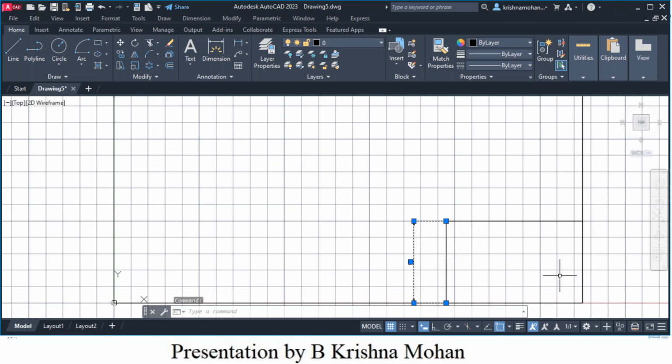I want to delete this dimension. I want to move this along the y direction. Select this line using the left mouse button. I'm holding this rectangle and let's move in the y direction. Make sure you switch on the auto option. When I move now, it is showing the distance.